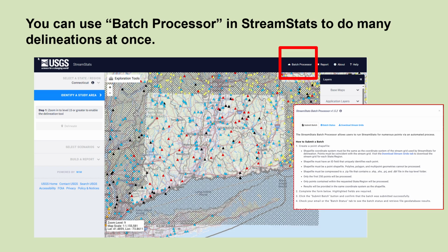So if we're following along from the original map, we have those orange diamonds indicating locations where we want to do SELDM simulations, and we input those to StreamStats to get the basin properties, and then estimate the highway site characteristics based on information that the DOT already has, or estimates from maps, or from just based on representative highway characteristics that are known to the user.